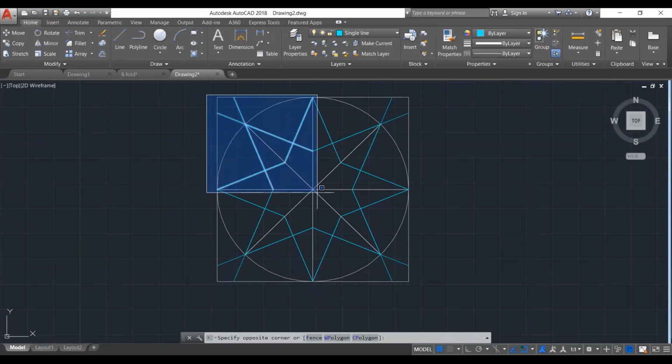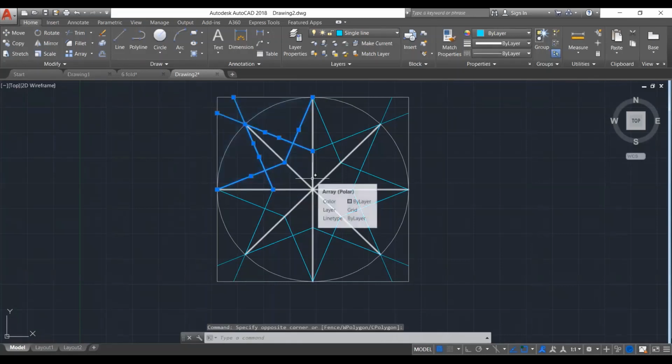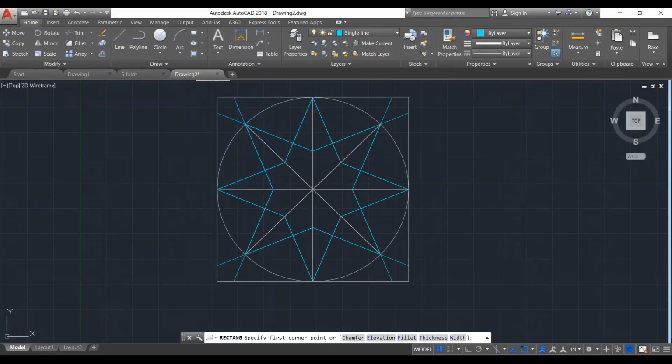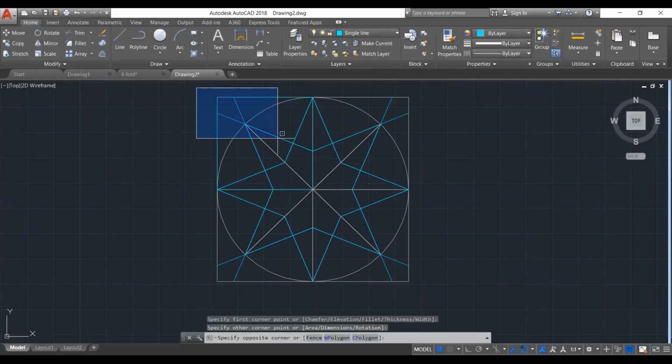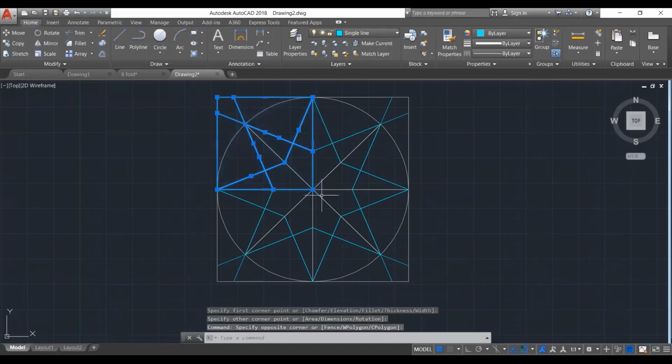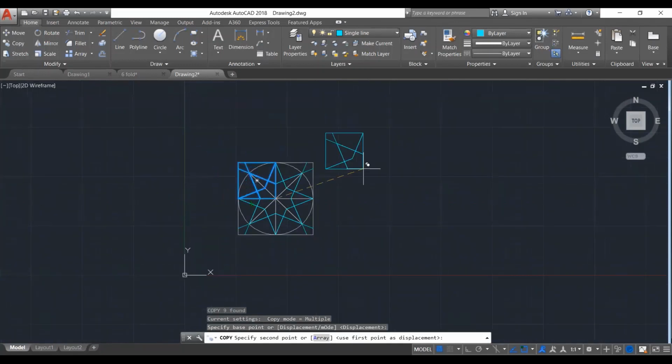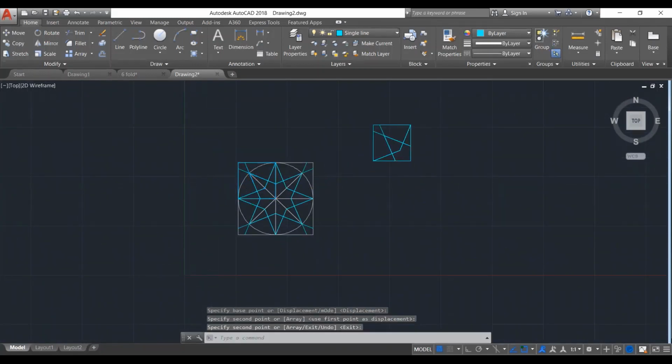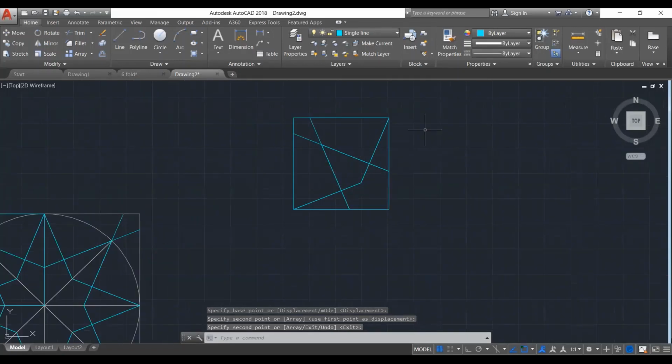I will highlight it, all of it, using this way. Because it's not all highlighted and I'm using this way, until they are all inside the square, it will be highlighted like this. And I don't need all the squares, so I can draw from here, using the shortcut for a rectangle. So this is my quarter unit only, and then I will highlight it like this, not to take any other thing. So I press CO, enter, and I will take it outside my pattern. So now I have only my quarter unit.